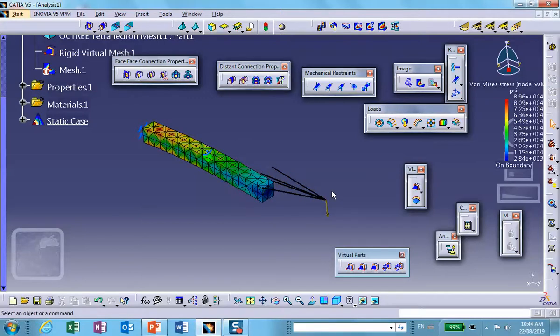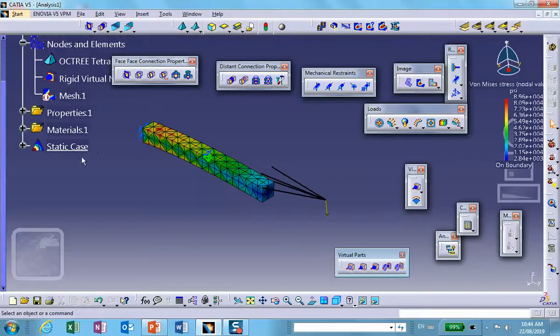Okay, now there was something I want to tell you about this other type of virtual part that you've got. There is one which is called rigid spring virtual part, which is not completely rigid. You input some stiffness as a spring element internally, of course. For its stiffness, you have to do some engineering and find out what the stiffness of that left out piece is. And this one is the smooth virtual part, which I didn't use. Now, when you do rigid virtual part, that square that I took at the end, that support, remains rigid. Let me hide this for a second. There are no dimensional changes at that support. However, when you do the smooth virtual part, you go through the whole concept, except that you allow that support to deform. Okay.